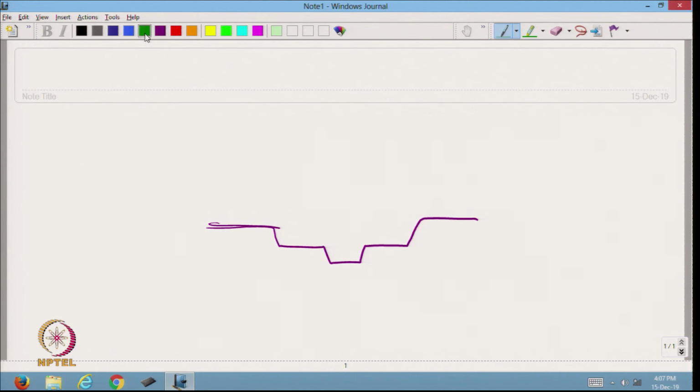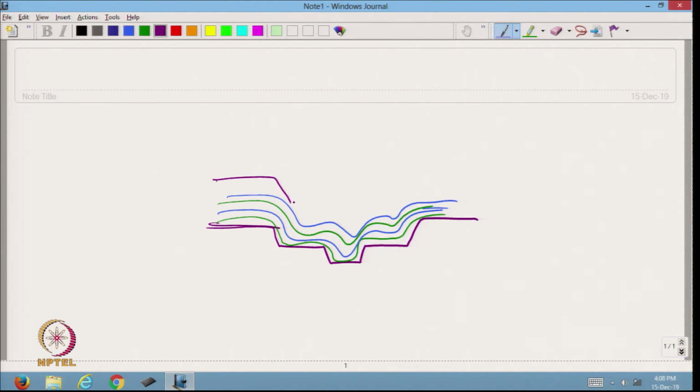After that we can lay the reinforcing material along with, say, one layer of matrix, this is reinforcing material, then we can put another layer of matrix, another layer of reinforcing material. So, we can do many combinations, and at the top there will be the other part of the mold.